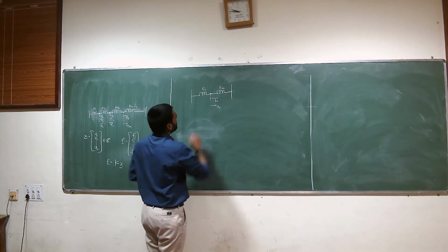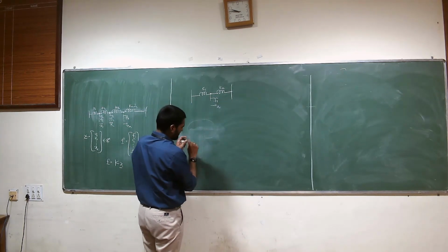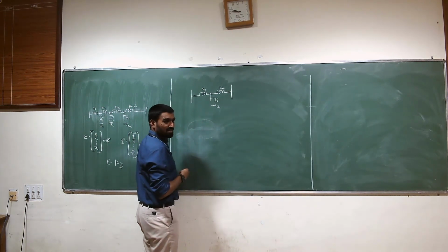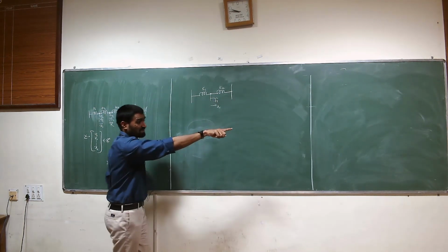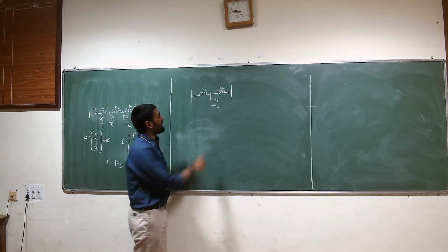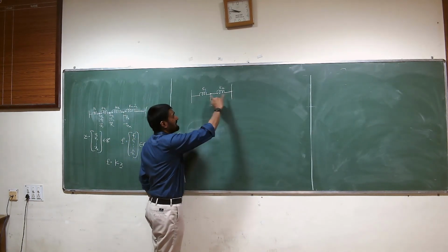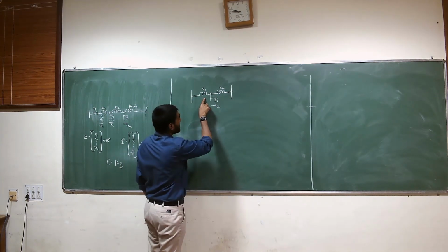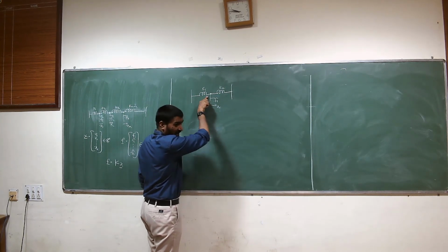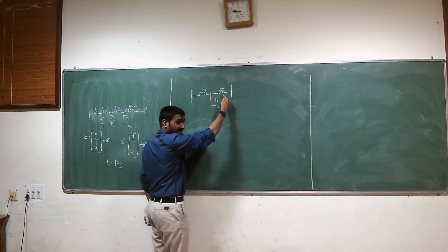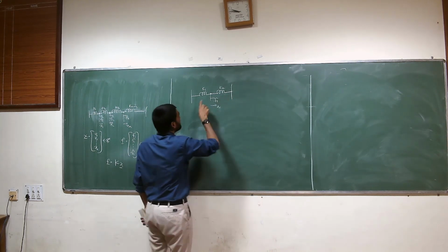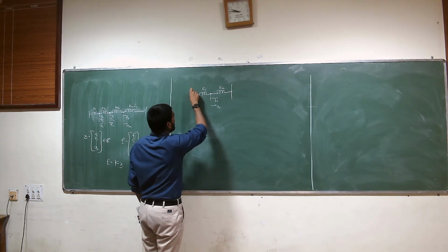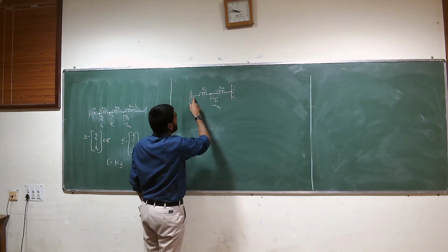Okay. Now, if you have this, if you imagine you have 2 clamps and there are 2 springs, and you apply a force in this direction, what would happen? If you apply a force in this direction towards the right, what will happen to spring 1? This one would stretch, this one would compress. The force F1 that you apply will have to work against the stretch in spring K1 and against the compression in spring K2, right?